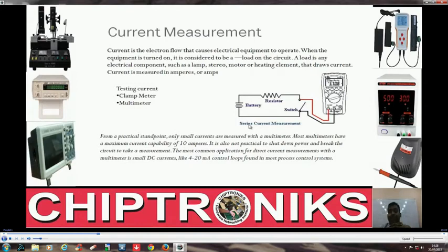And when you are doing nothing on a notebook motherboard, suppose it is in a normal idle state, in that case the current consumption by the processor is very little. So the value of current increases and decreases according to the type of application you are running. What is fixed is voltage.